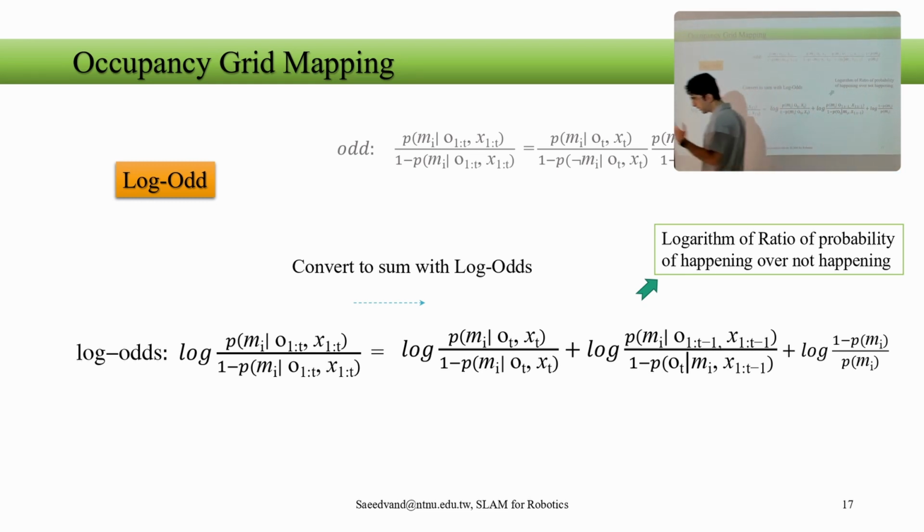But what we've done, for each one of the grid cells, instead of directly applying the Bayes filter to calculate probability, we bring it to the log-odd form with some math calculation to make it stable to calculate first. Second, and most importantly, it is less computationally expensive and a more stable solution for the SLAM problem.